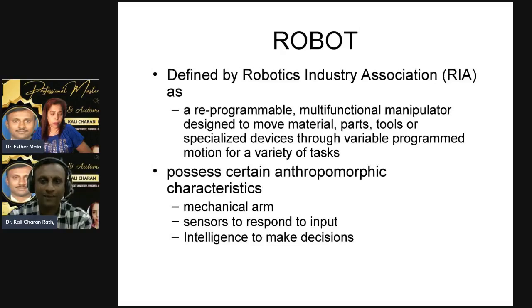Now the robot has a manipulator and an end effector. Manipulator, here we can say that the robot consists of certain types of movement: link, joint and structural elements. A link will move from one position to another position, and to move the link, a joint is required. The joint is responsible for the movement of the link, and it keeps the interlink between one link and the concerned forward link. So between link 1 and link 2, the joint is there. Clear? Now this is the manipulator.